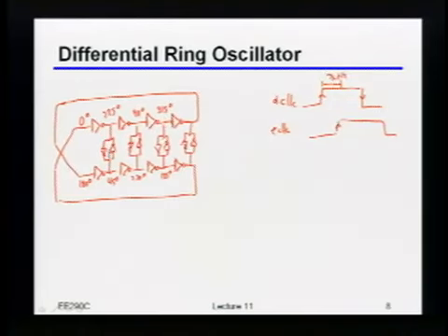So when I add these cross-coupled inverters here like this, is that a good thing or a bad thing from the standpoint of speed, power, etc.? Use of frequency. It reduces your frequency, right? So now for the same clock frequency, you're going to have to up that power supply voltage. So you have to spend more power, not to mention that, of course, you have crowbar currents because they're fighting each other.